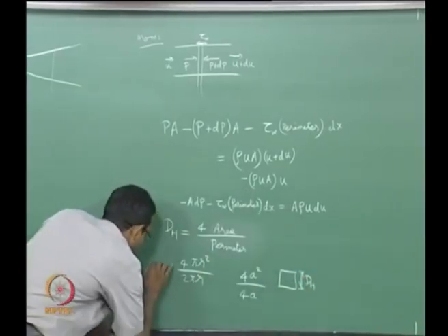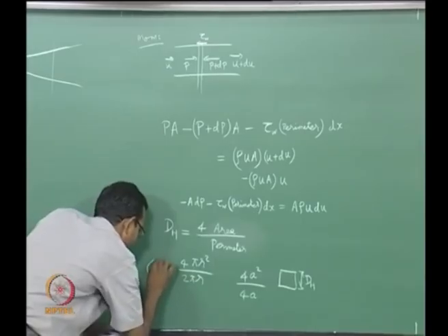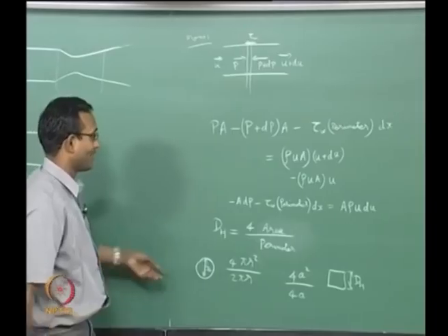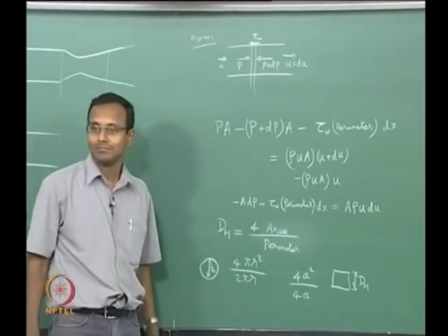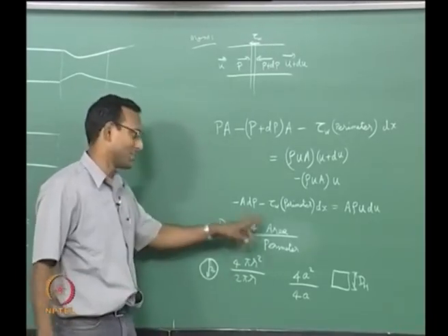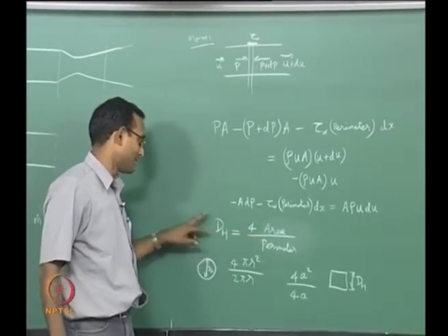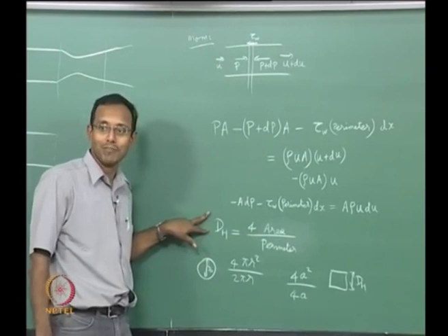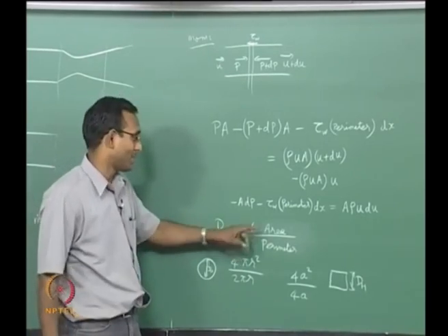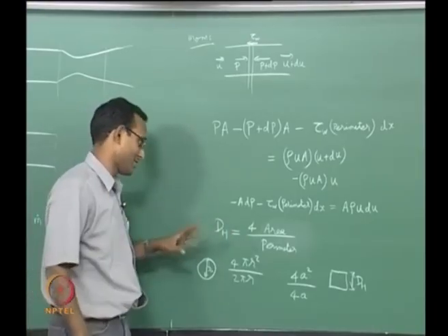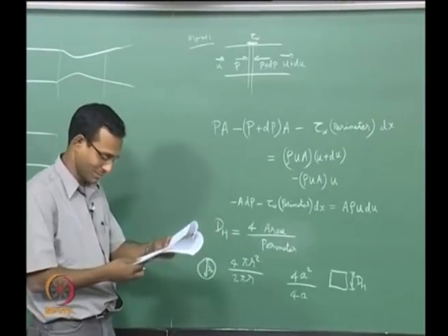If I think of a circle cross section, this is my hydraulic diameter. This is how they defined hydraulic diameter. That is why you have this 4. Just remember that, then you will never go wrong in this formula. The mistake I made should never happen because it should have dimensions of meter. I had a perimeter by area, that will have 1 by meter as dimension. That can never happen. So, simple checks, always keep in mind, you are all basic engineers.